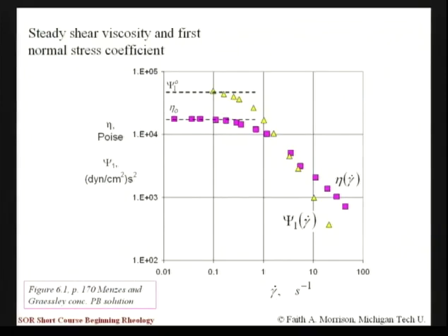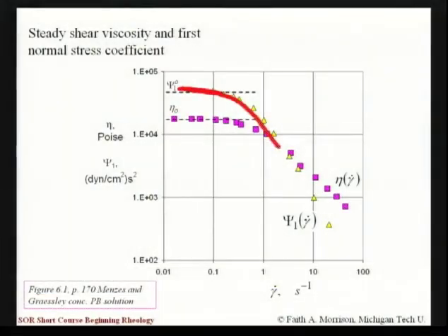Actually, I didn't discuss this yet. This parameter, there's a subtlety to this parameter, the shear rate. This is not gamma dot naught, and that's not a typo on my part. Let me talk a little bit about that. Just before I do, let me point out why the first normal stress difference was tau 1, 1 minus tau 2, 2 divided by gamma dot naught squared. Okay? By dividing by gamma dot naught squared, we got this function to look like it does, which is that it goes to a constant value of the plateau and looks kind of like a shear thinning viscosity value.